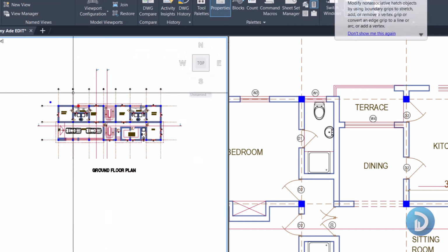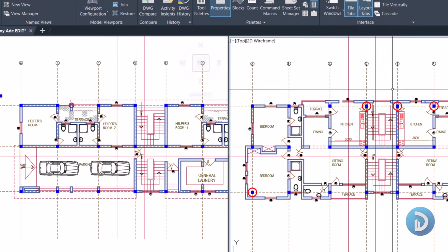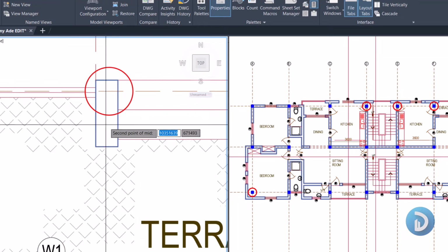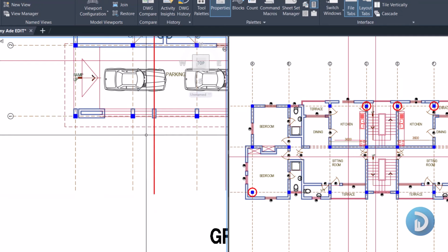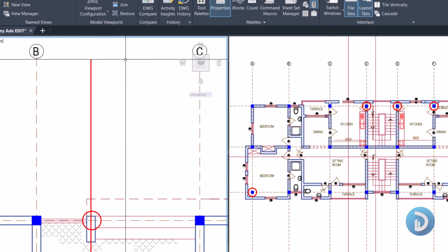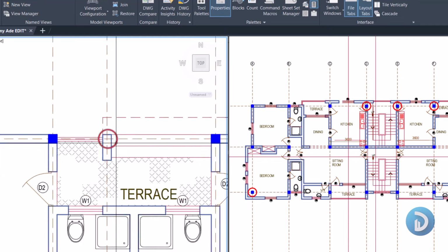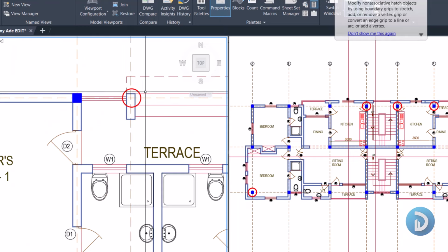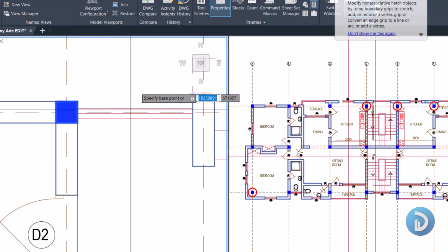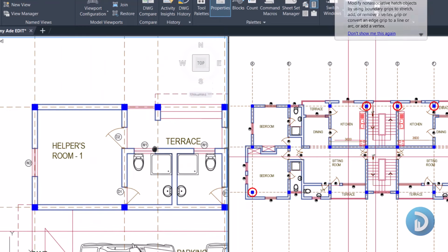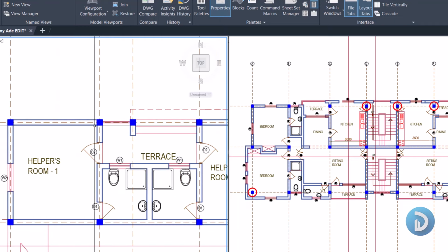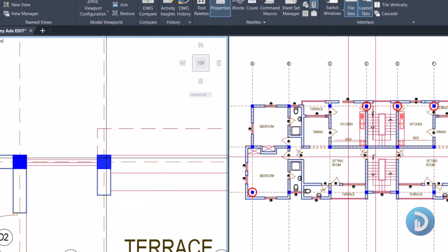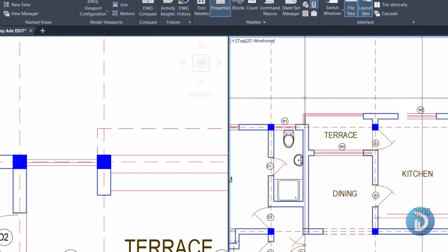Remember, whatever we've done here is actually tentative and is subject to change. Okay, as you are making modification on the first floor, this is subject to change. And let me create a grid line between these 2 points. I'll drag this up, then I'll match the properties of this to this. Let's erase this and this as well. Okay, so now we can copy our column from this part to this part. So we can run a beam directly from this part on this wall that will be constructed here. We can run a beam from this grid line A up to our grid line C. Then from here, we can send a cantilever out in order to carry this part that is coming here.